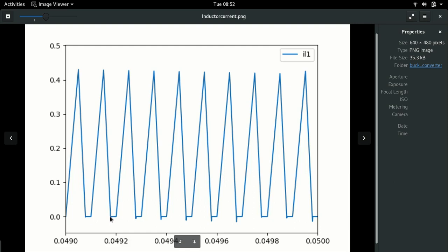And this little glitch here that you see is the reverse current when the diode turns off, because remember, the way the simulator works, and typically the way any simulator works, the diode will turn off when the current goes negative. So when this rate of change is pretty high, it is impossible to arrest it as soon as it becomes 0. There may be a little bit of a negative spike, and that's what this is. So this is not really a huge negative current like the way we saw before. This is just a case of these spikes appearing as if there's a huge negative current.